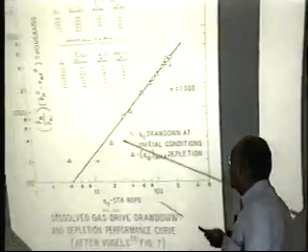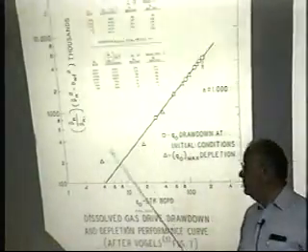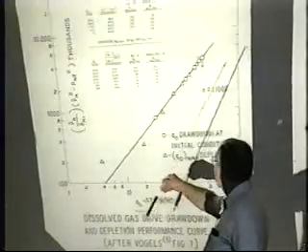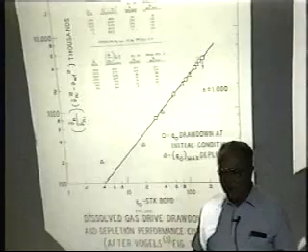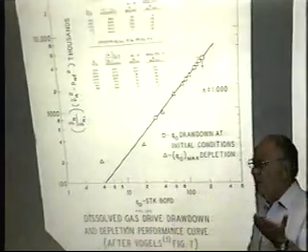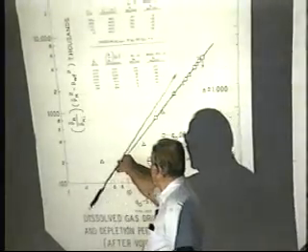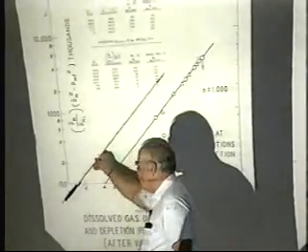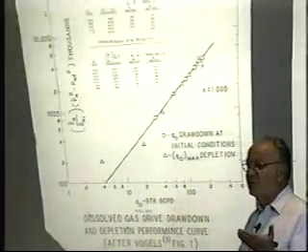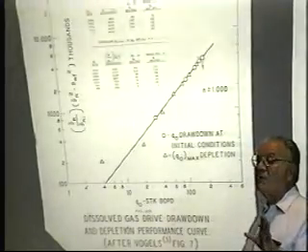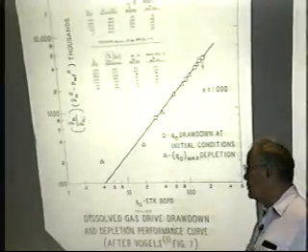To include the effect of the relative permeability shift, the curve would be like this at initial conditions. As you deplete and the saturation of the oil starts to decrease, the relative permeability effect is going to be that you would have a sequence of curves that would be shifting constantly to the left, just because of the saturation changes. You don't have this in the gas well. The relative permeability is always equal to 1 in the gas well, so you don't have that shift.